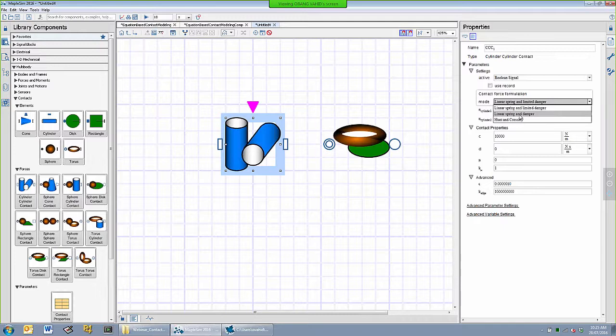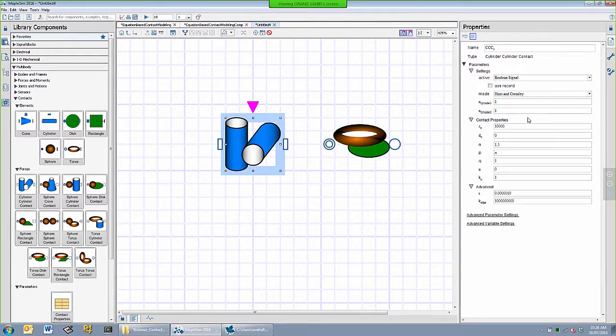This would be just, I would think, for testing to see what the effect of it is. If someone wants to have the pure linear spring and damper, they can choose to do so. However, that would not be the best choice in most cases. If you do have information about the type of contact, the Hertz type contact can be applied, where in addition to having a linear spring rate or a damping constant, you do have a full nonlinear relationship with exponents for the displacement and also exponents for the velocity term in your contact.